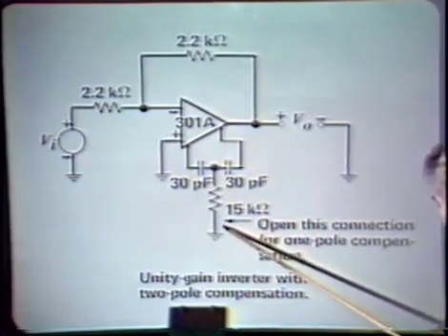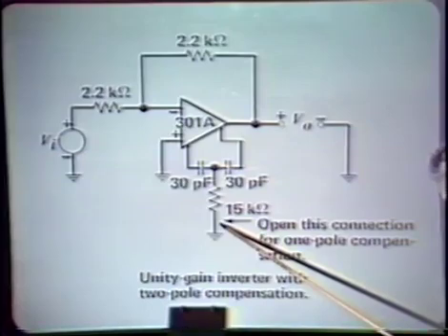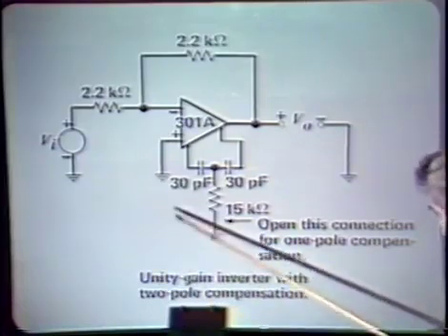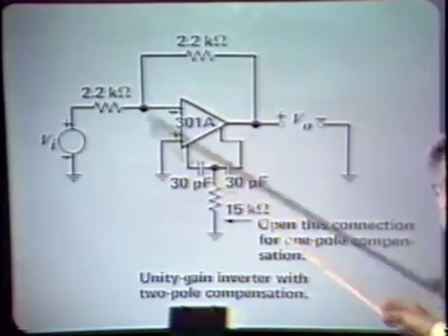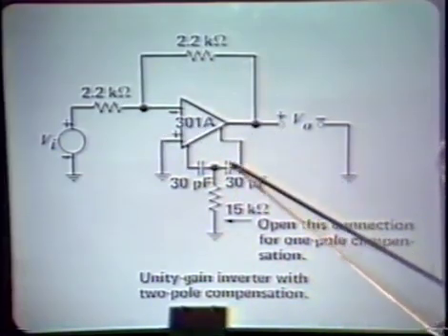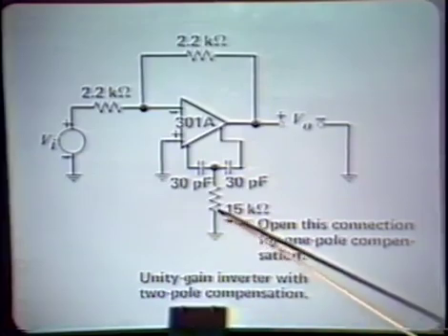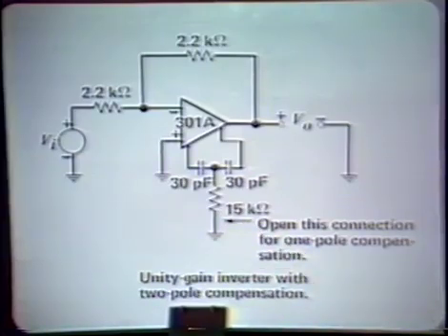The 0 comes in at about 100 kilohertz. So this combination of values gives us the 1 over s squared roll-off, which breaks back to 1 over s in the vicinity of crossover.